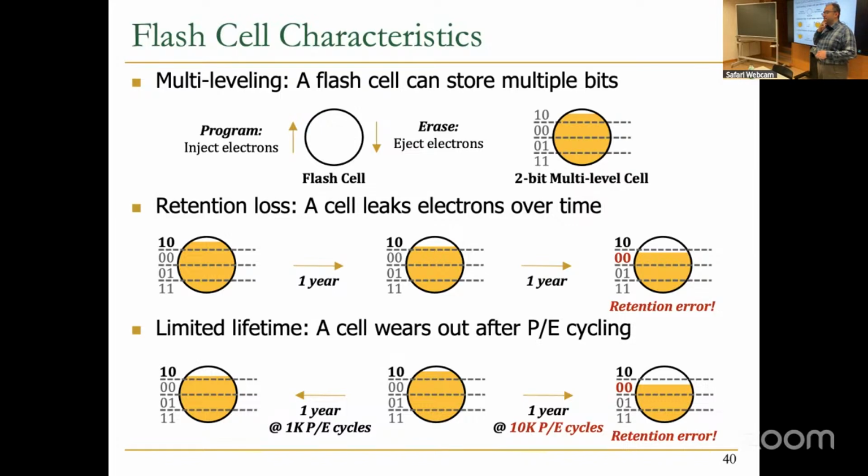It's actually at the FTL level. People are working on open channel SSDs, where you can implement the FTL at the host. With that, yes, you should be able to be aware of everything internally. But from the research that I'm going to show later, we actually built an infrastructure similar to DRAM vendors, for example, and we were studying a lot of these flash memory characteristics using an FPGA infrastructure.